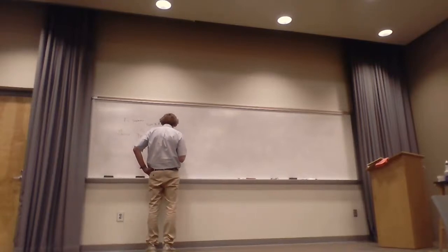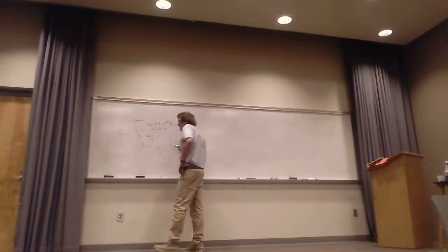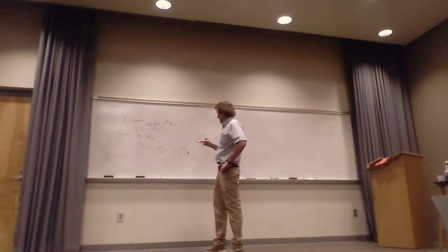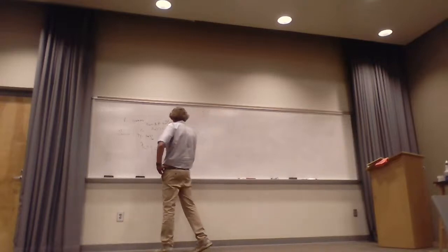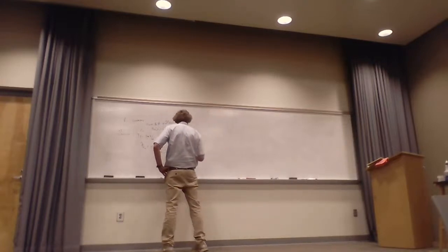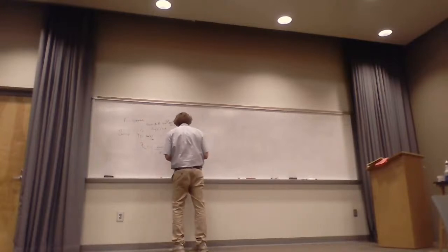So that's equal to the square root of 2 pi f times mu 0, mu relative is 1, over 5.8 times 10 to the 7th. And f is 200 megahertz, so it's going to be at an angle of 45 degrees, or pi over 4.